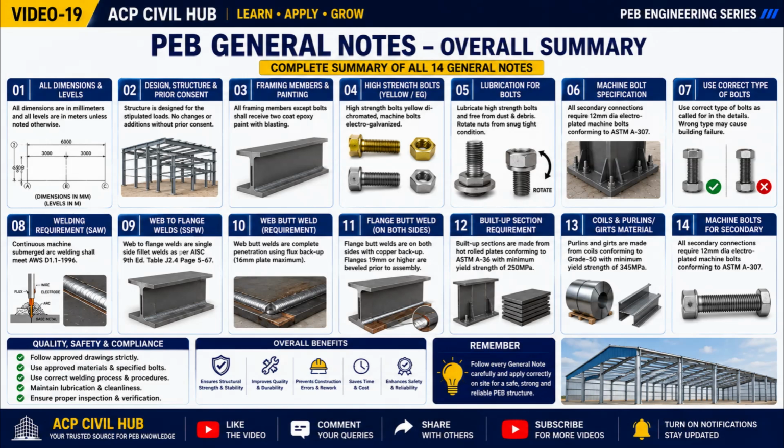Finally, we studied built-up section materials, ASTM A36 requirements, and Grade 50 material specifications for purlins and girts. These general notes are much more than standard instructions. They define the project requirements for fabrication, material selection, welding quality, corrosion protection, connection safety, and overall structural reliability.